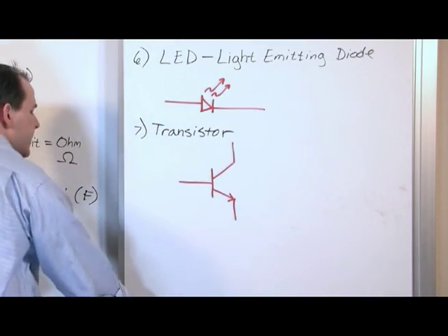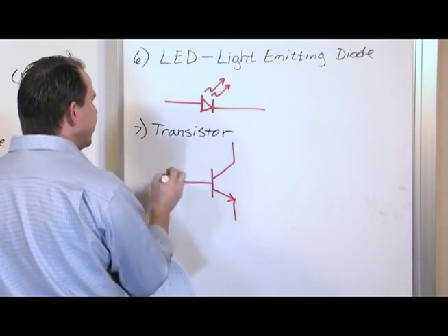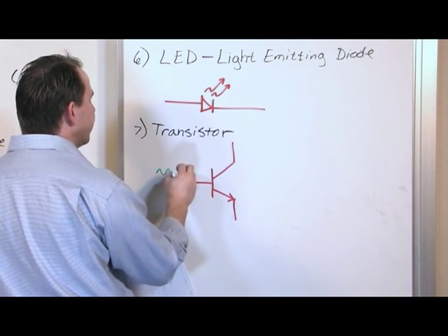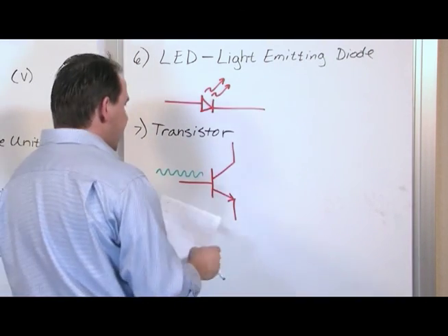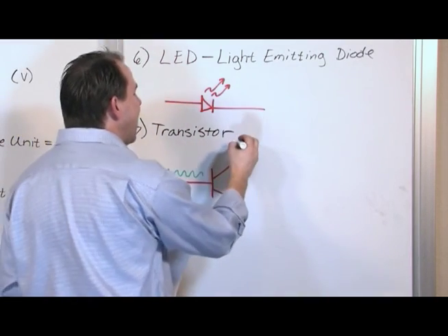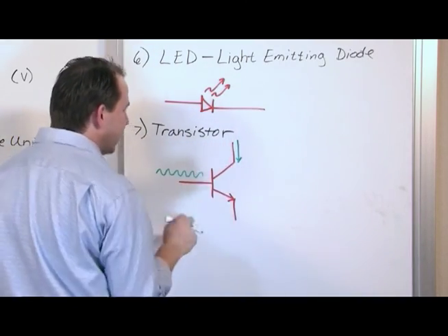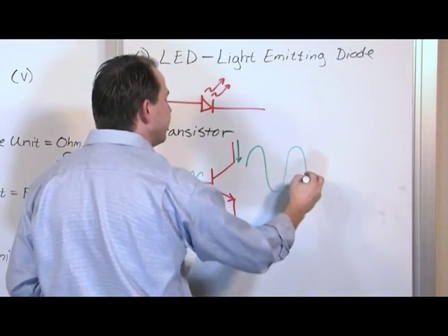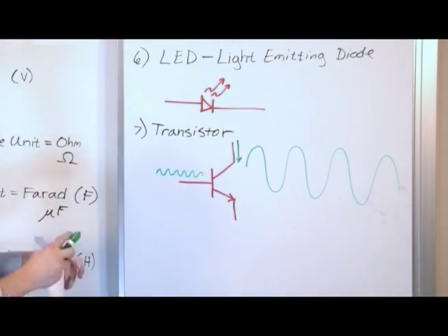All right. Now, I'm not going to get into transistor theory here, but basically what I was saying a minute ago, if you're sending your voice in over a wire, let's say, you may have a very small voltage signal coming in on that wire. And the way you send the input comes into this leg right here. The output has current flowing down through the thing like this. This is the output. If you stick a voltmeter here, you might see something that looks like this, much larger. But it's a direct replica of the input, and that's how it behaves as an amplifier.